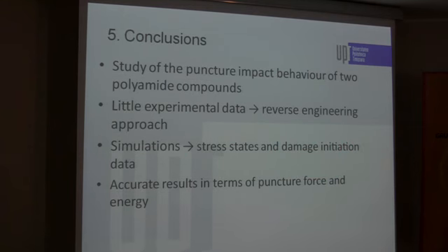So as a conclusion, we had a study of the functional behavior of two polyamide compounds. We had little experimental data, and we tried to use a reverse engineering approach to calibrate the material models, the stress response and the damage parameters. And we obtained accurate results in terms of puncture force, energy, and the failure mechanism of both materials.